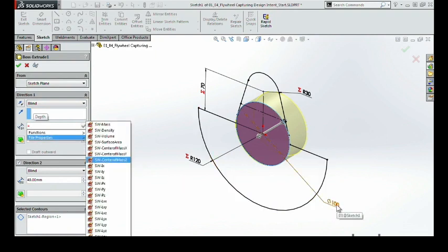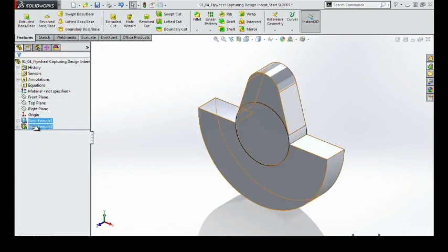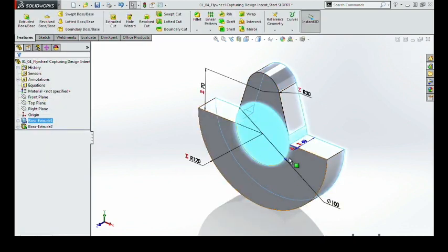In the graphics view, you will note the sketch dimensions are now visible. Select the circle dimension, which is 100mm, and multiply this by 0.01. Enter once to solve the equation. Do the same for D2 and multiply by 0.4. Enter and enter again. Let's see how our model behaves now when we adjust the 100mm dimension using Instant 3D.